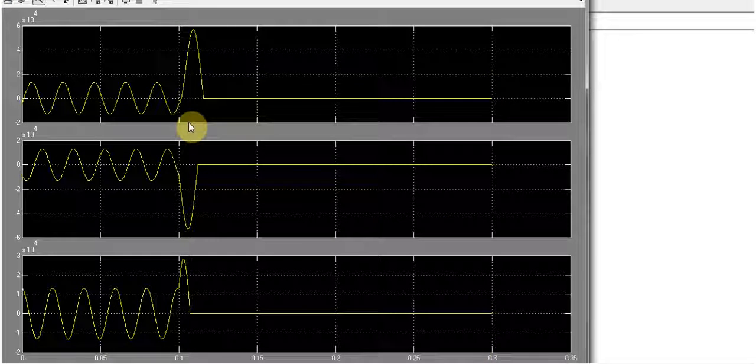You might also have observed that the fault occurs here and the current is still increasing, and then the relay doesn't stop the current until it touches the 0 value. So the relay is operating until the value is zeroed, and you have to almost complete the cycle until it reaches the reference value of 0 ampere.